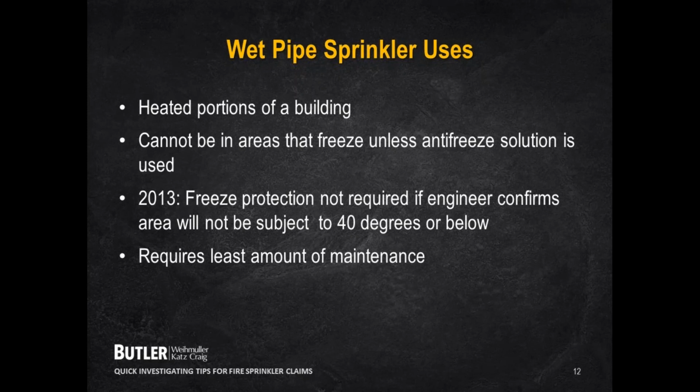In the NFPA 2013 edition, they noted that freeze protection is not required if an engineer confirms that the area will not be subject to 40 degrees or below. That is a fairly recent NFPA regulation.